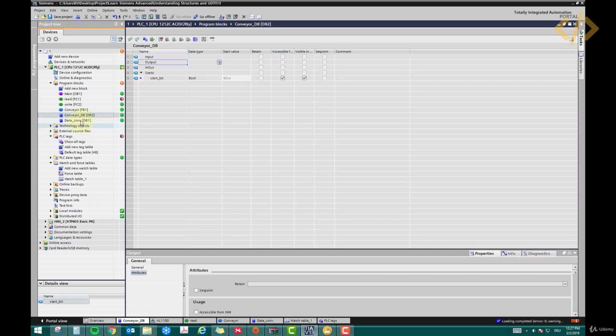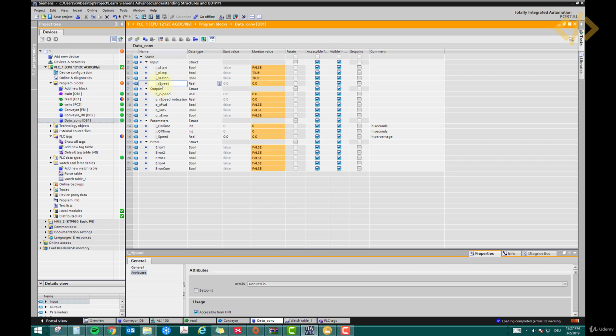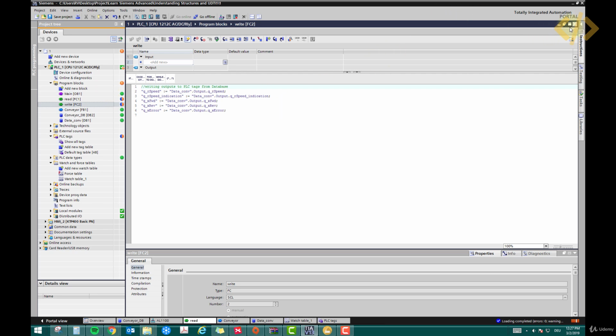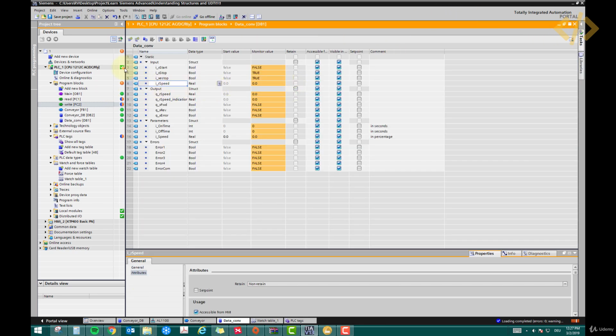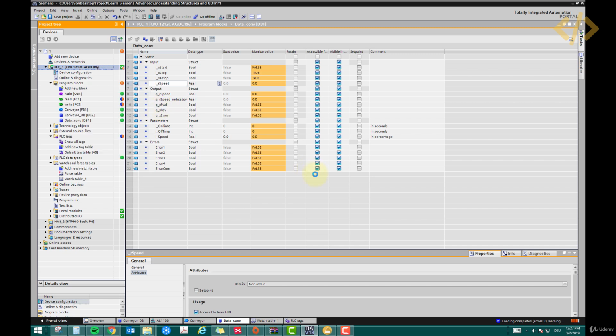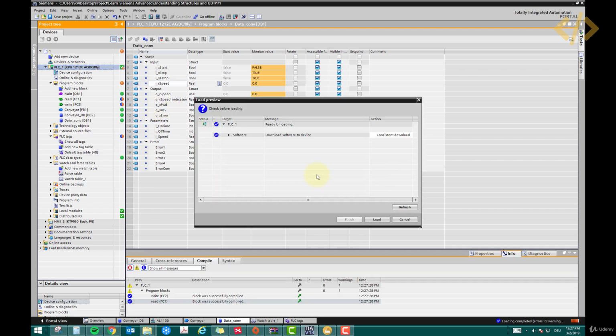So this DB converter will automatically read from 200 now, because this is defined in the read function and the write function. This is the benefit of using functions and moving the value from tag to DB, so that your internal programming remains the same, internal assignment of addresses remains the same. You just have to make changes to your tag.